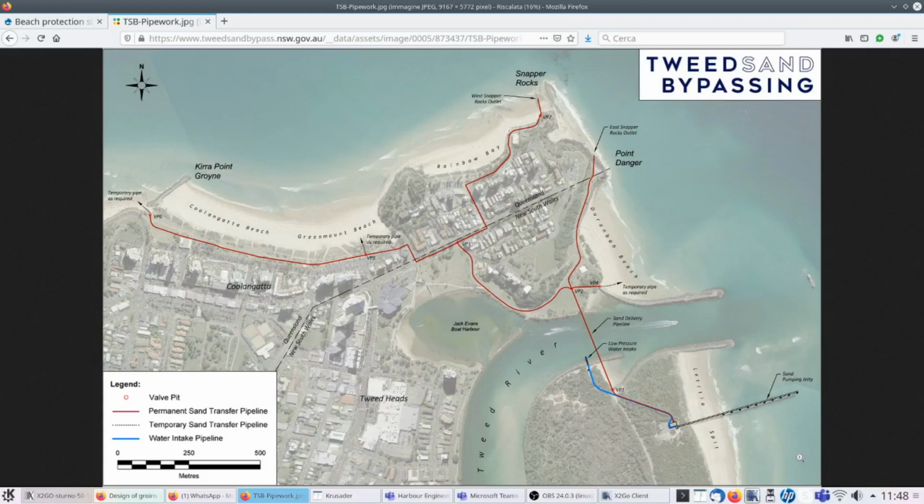That groin was built in order to stop erosion, because the groin stops the longshore sediment transport, and therefore it gives rise to accretion of the beach before the groin and erosion after the groin. So you see clearly the difference in the beach shape before and after the groin.